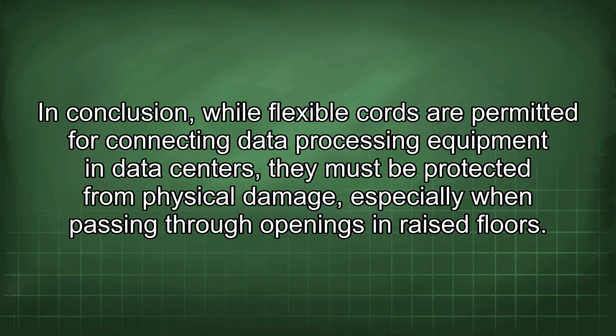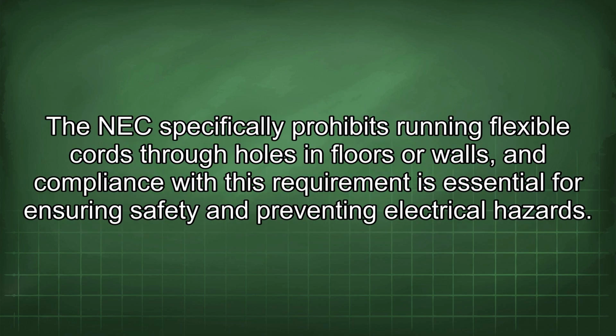In conclusion, while flexible cords are permitted for connecting data processing equipment in data centers, they must be protected from physical damage, especially when passing through openings and raised floors. The NEC specifically prohibits running flexible cords through holes in floors or walls, and compliance with this requirement is essential for ensuring safety and preventing electrical hazards.